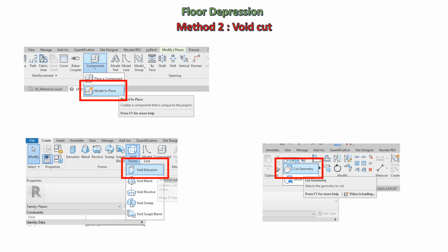Again, such void also creates opening inside the shell element. At this point, always name your void systematically, so that those could be easily deleted all at once later on in the pre-finite element Revit model.